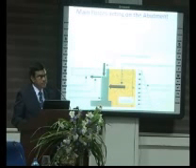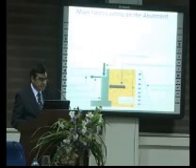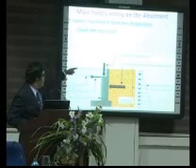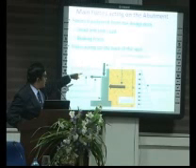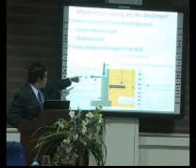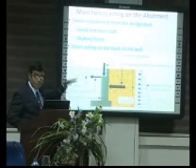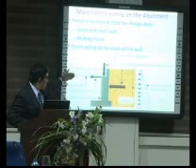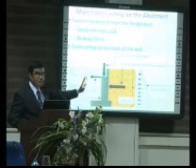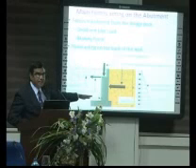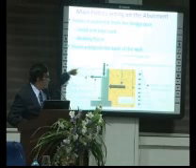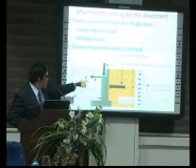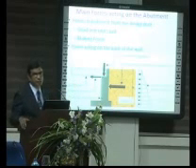So what are the main forces acting on the bridge abutment? Now you can see this vertical force is coming from the bridge deck, and this horizontal force is basically due to the braking of vehicles on the bridge deck. So there are two forces, horizontal and vertical, from the bridge deck. Now if you see the back side of the abutment, you have a soil fill that makes the approach to the bridge, and that has massive horizontal force.